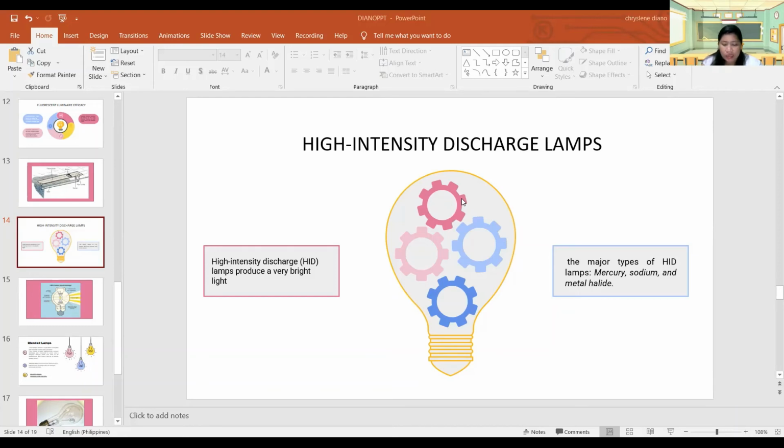In modern lighting usage, the HID lamp functions by sending an electric arc between two tungsten electrodes which are housed in the arc tube, usually constructed of quartz. The tube is filled with an amalgam of gas and metal salts.